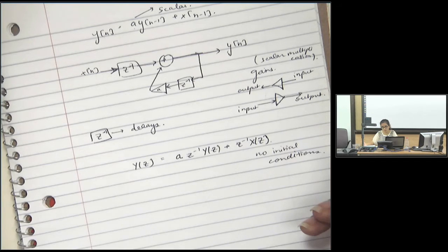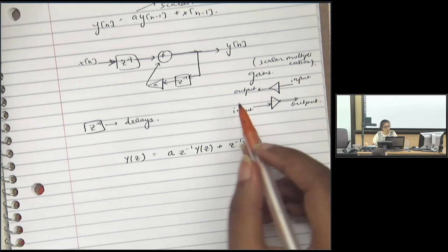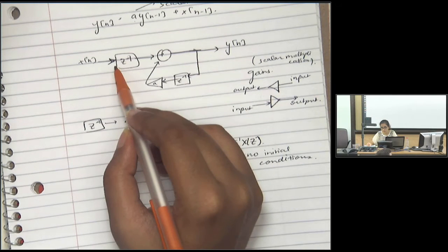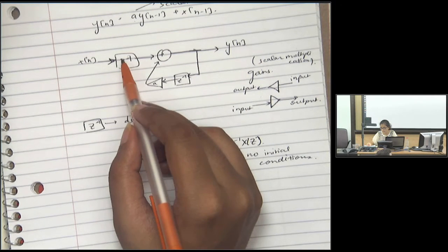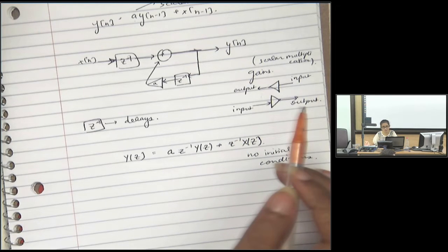But with the integrator, it looked like the sigma, and then when you transform it, it became 1 over s. This one stays the same. It's z to the power minus 1 in both domains. I didn't get it. If you want to transform that system, this itself is a system. So in the discrete domain, it's equivalent to a convolution, but in the z domain, it will become a multiplication. That's why it remains the same. Okay?